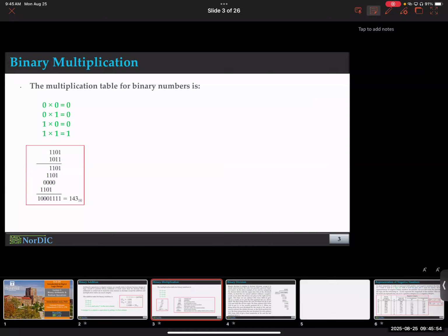That comes last. Multiplication. My personal opinion is multiplication is much simpler for binary, even simpler than in decimal, because all you have to do is multiply zeros and ones. This is super simple. And if you notice, this is essentially an AND operation. Multiplication is nothing but an AND operation. So if you create an AND gate in the Boolean platform, you can use that AND gate to do multiplication. Simple.